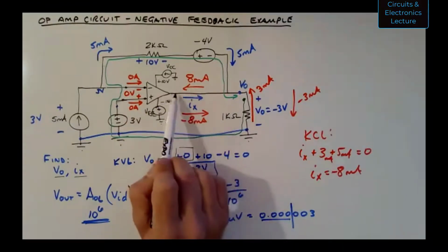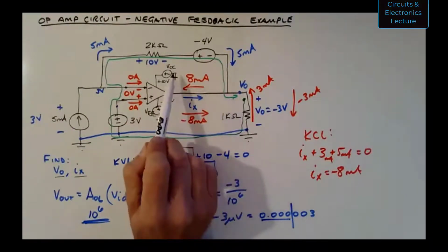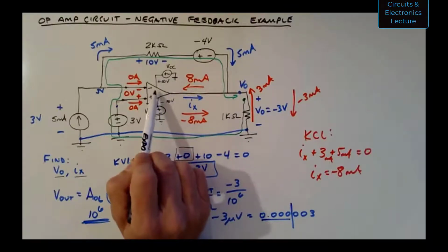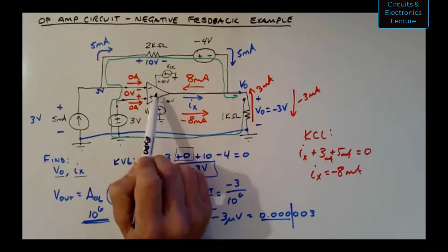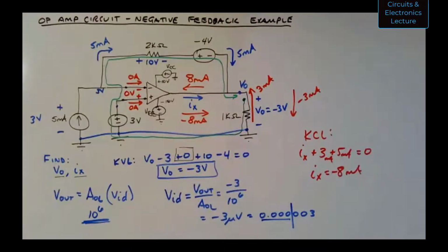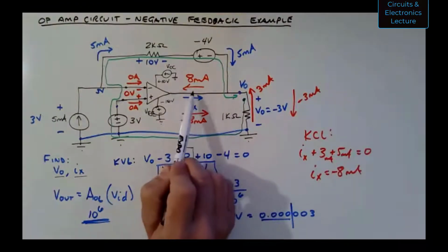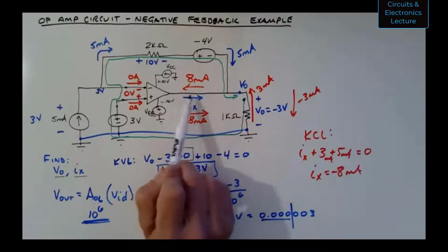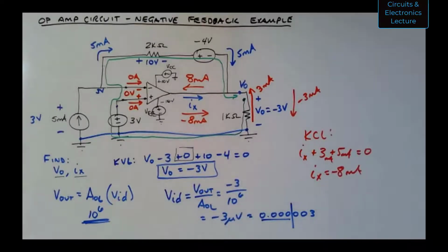If you had 8 milliamps, let's say, coming out of the op-amp, you'd have current coming from VCC, from that source, down into the op-amp. I showed you all those transistors in there, going through those transistors, and then coming out of the output of the op-amp. So that's where that current either goes into, that's called sinking a current, or comes out of, that's called sourcing a current, right? Okay. Any other questions about this problem? We'll move on to comparators.